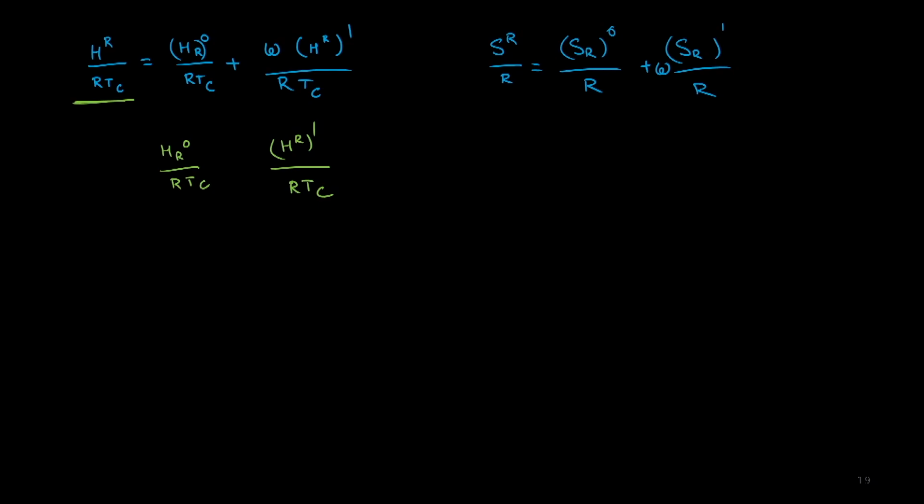So similar to tables for the compressibility factor, Lee-Kessler tables exist for residual enthalpies as well as residual entropies. They can be directly used to calculate the residual values. In that sense, they are convenient, but then we need to do a linear interpolation or a double linear interpolation as need be. Compared to dealing with elaborate equations, Lee-Kessler tables in that sense are handy.